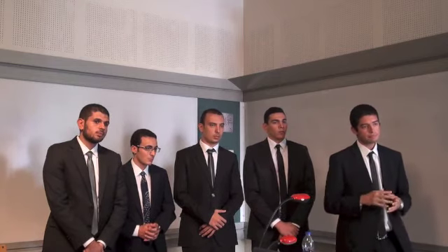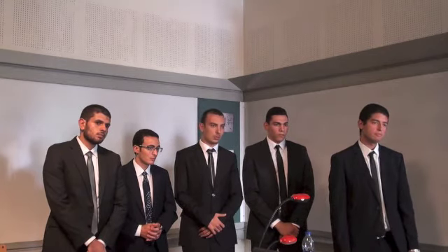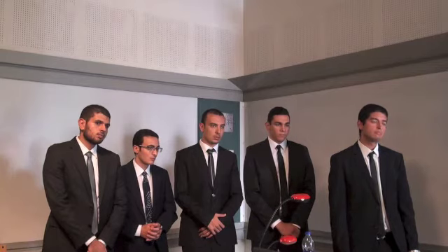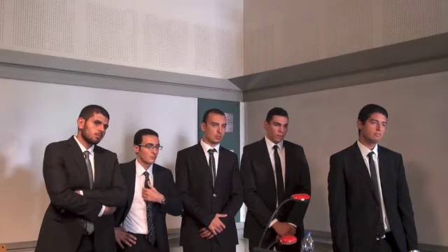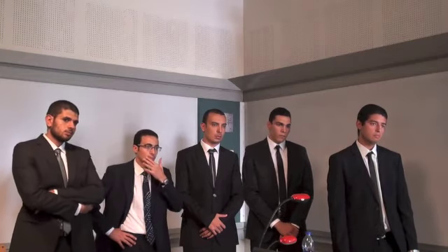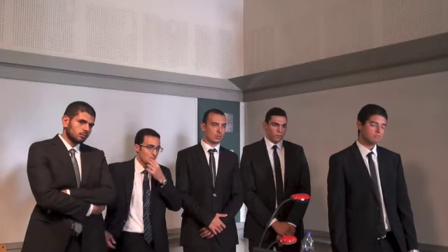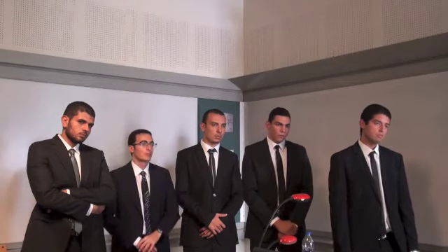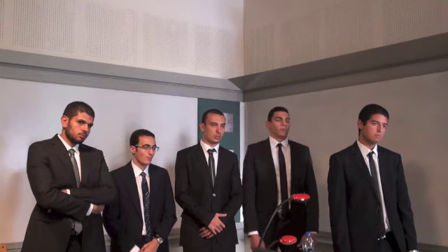I am just saying that because I'm not sure that scaling is correct. You might scale the dimension, that's one thing, because it's a slab on grade. But scaling the thickness, I'm not sure how correct that is, because the behavior of the slab as rigid changes with the thickness. If I even reduce your scale to 1/10, not 1/2, and make the slab only 1 centimeter thick, you may say scaling wise, it's a scale. However, the behavior of a 1 centimeter thick slab is different flexibility wise than the 15 or 20.